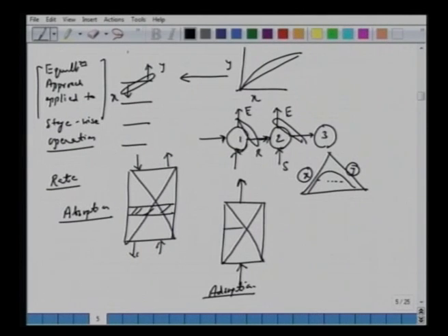From one stream to another, one phase to another phase, we have finite mass transfer, N equal to minus k (y minus y star), some kind of definition for mass transfer coefficient. So in principle one has to write a very rigorous species balance for this. Here we don't get into details of interfacial mass transfer or the time over which this stream is getting mixed with this stream and there is a mass transfer. It's more like a steady state process.